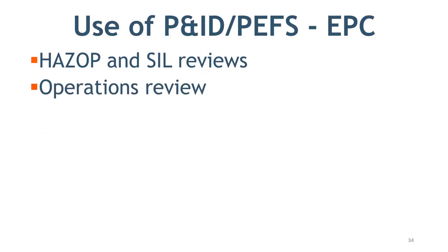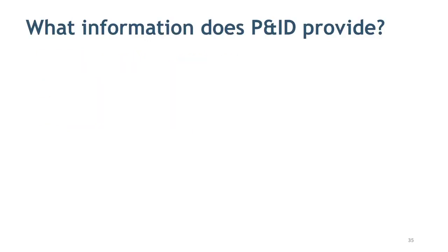During operation, you have to maintain P&ID in such a condition that it will show the actual plant condition at any time. It should be updated when any physical change is made so that the unit will remain compliant with code, standard and specification and can be operated safely under the defined process condition. P&IDs are used to train operators and engineers before they start work in the actual plant.